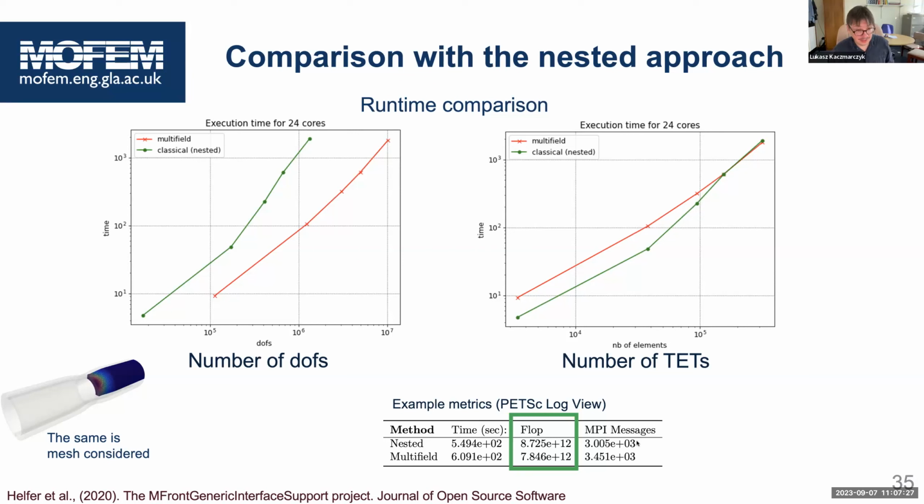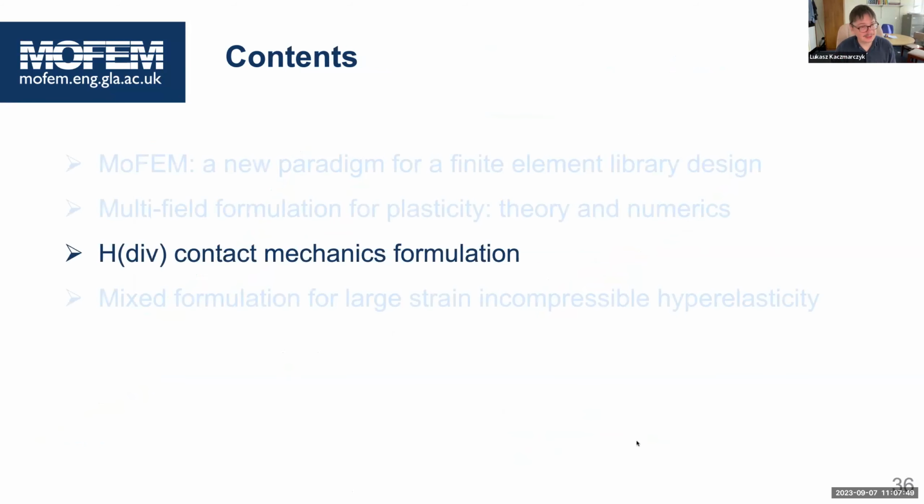In 3D, it's not working because we have not yet implemented the wedge element in the code. Sometimes when you make heterogeneous meshes mixing tetrahedrons and hexes, you have to put in a wedge, and that is not working. But the key thing is that you can raise the approximation order, and you can approximate geometry in an arbitrary way.